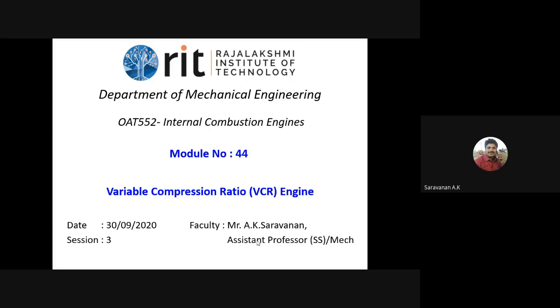So to improve this efficiency, the SI engine operates with a high compression ratio at part load and a low compression ratio at high load. So we require different compression ratios depending upon the load condition, the efficiency and the power condition.